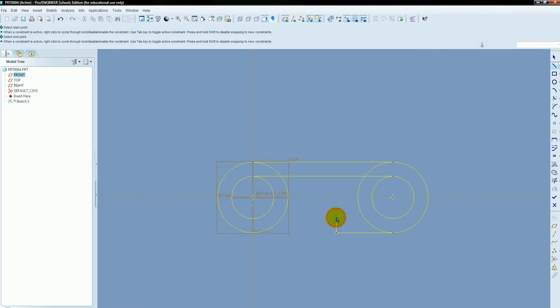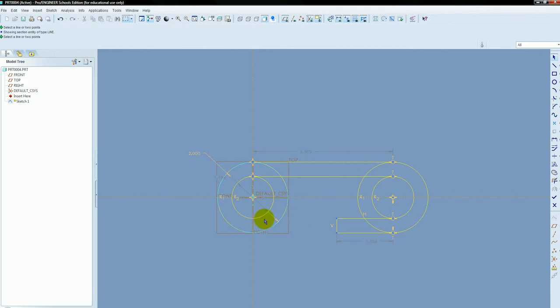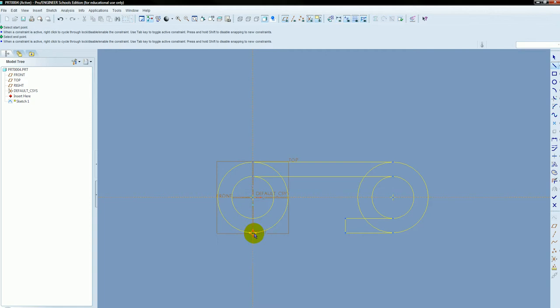So what I'm going to do is I'm just going to draw this here and then connect it tangentially and then put a horizontal constraint on it. And I'm going to show you another way that you can do it on the other side. So there's my horizontal constraint. Okay, now with this stuff in place, I want to draw this stuff out this way, and since I already have one of those over here, what I can do is I can set this up to automatically have equal lengths and stuff on it. So when I start my line here, I'm going to bring this out until it has that L for equal, that L for equal, and then this will come right back to here, and everything should line up pretty good.